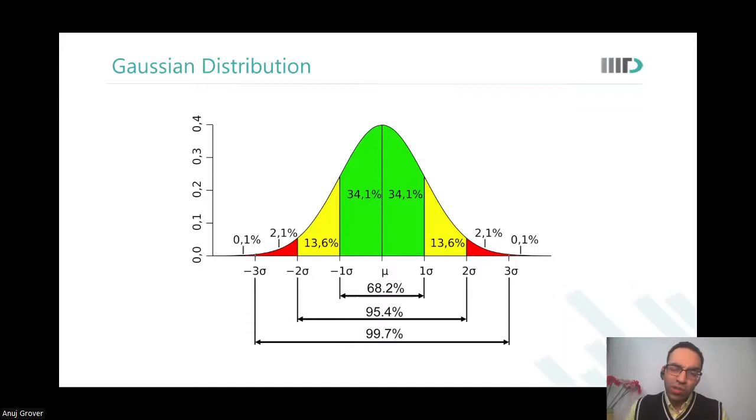But Gaussian distribution is not the only distribution that we are worried about in VLSI, but it is the primary distribution because of which mismatches are introduced in our circuits, in our devices, in our designs. So, for example, we talked about gate oxide thickness. There will be places where there will be 2 atoms, there will be 2.5 atoms, or the orientation is such that the gate oxide thickness would vary from 22 to 28 nanometers. That was the micrograph that we saw in the last class.